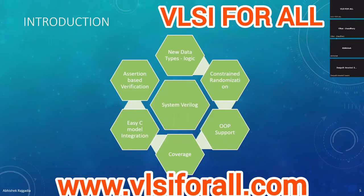To do that, you can instantiate objects of the classes which implement that protocol, call some function, and it will send a transaction to the CPU. You don't have to implement that every time you create a test bench around the AXI interface. With that level of abstraction and reuse, you just instantiate it and you don't care what is happening inside. So OOP provides abstraction and reusability, and definitely helps with scalability also, because there can be multiple AXI interfaces and you just instantiate it multiple times.